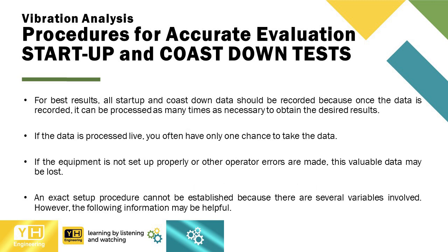For best results, all startup and coast down data should be recorded because once the data is recorded, it can be processed as many times as necessary to obtain the desired results. If the data is processed live, you often have only one chance to take the data. If the equipment is not set up properly or other operator errors are made, this valuable data may be lost. An exact setup procedure cannot be established because there are several variables involved. However, the following information may be helpful.